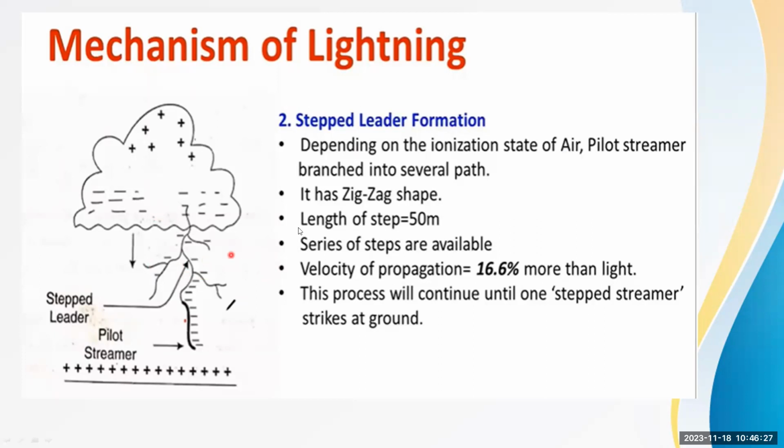Understood this step leader? Depending upon the ionization state of air, the pilot streamer branches into several paths like a tree. This is called step leader, and it has a zigzag shape. The length of the step is approximately 50 meters.